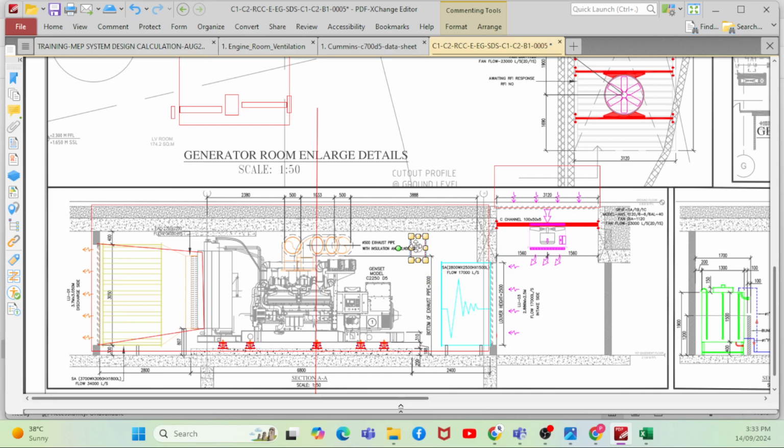So when the fan runs, it takes the air from this area to here, and it will only pump the air to divert. Okay, so in this case, you will have to change the F factor that you consider in your calculation, because you won't be able to directly throw the air as you've shown in this example. Instead, you will have to have a higher F factor, which means the flow rates will change accordingly. It depends upon the factor, how you are going to mount the fan.